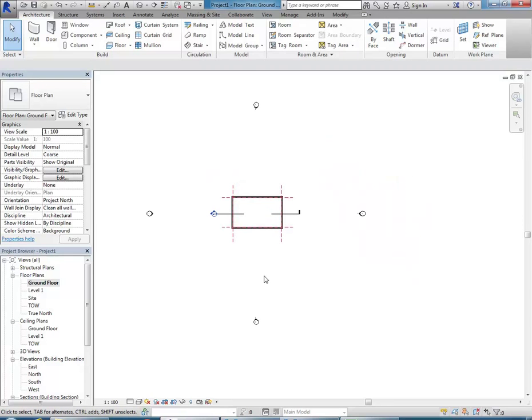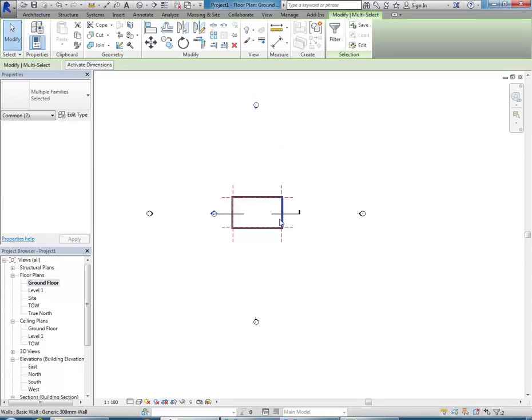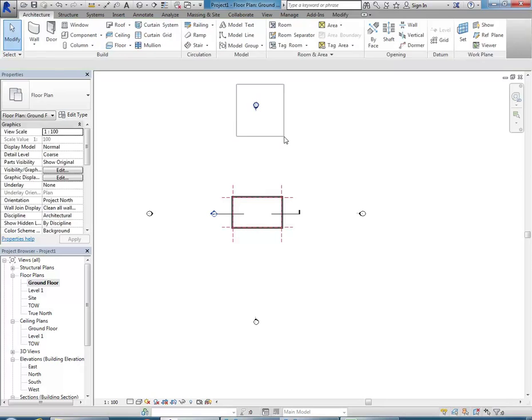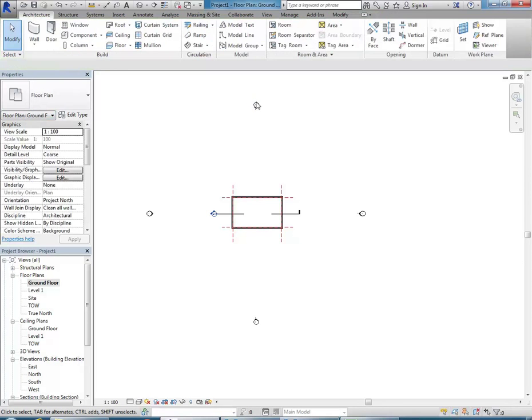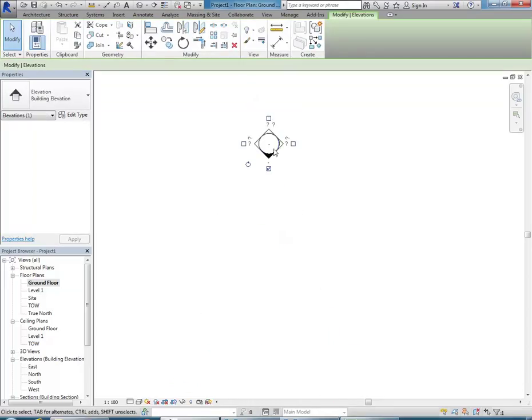And so then the final thing is the elevation views. And again, you can do this at any point. If you select those, it's best to do it with a window, because there are actually two things there. There's the symbol and then the view. And they are separate things. So you can see over here it's got common 2. Because I've selected with a window, if I just click onto it, it'll only give me one thing. So that's just a little tip there.